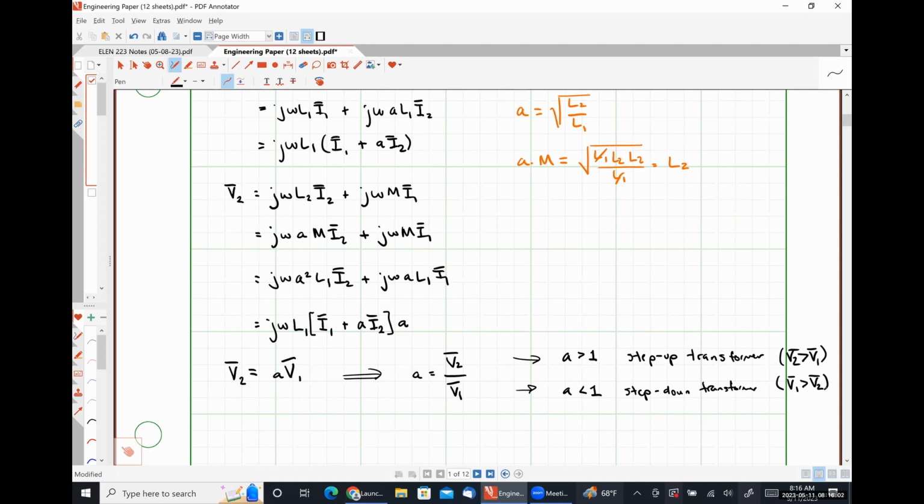Absolutely right. So if we were to look at the voltage on the transmission lines coming from the substation north of town here, the voltages leaving that substation are, I believe, 13.8 kilovolts RMS. But in our outlet, which is connected to that substation, we only see 120 volts RMS. So there obviously has to have been some sort of step-down transformer somewhere between where we are getting our power, that substation, and here. And those are those transformers on the poles that you see outside. Those are literally step-down transformers that are converting that 13.8 kilovolts RMS into a 208Y/120 voltage accessible by all the buildings here on campus.